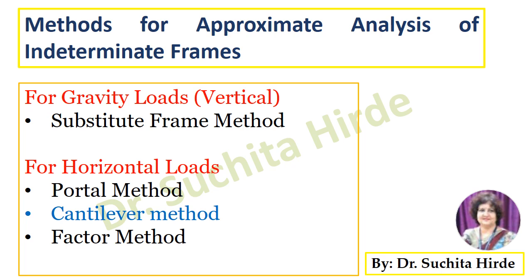So to analyze the frame subjected to vertical loads or gravity loads, we have substitute frame method. And for the analysis of frames subjected to horizontal forces, we have three methods, that is portal method, cantilever method and factor method. So in this video, we are going to learn cantilever method for analysis of multi-story frames.